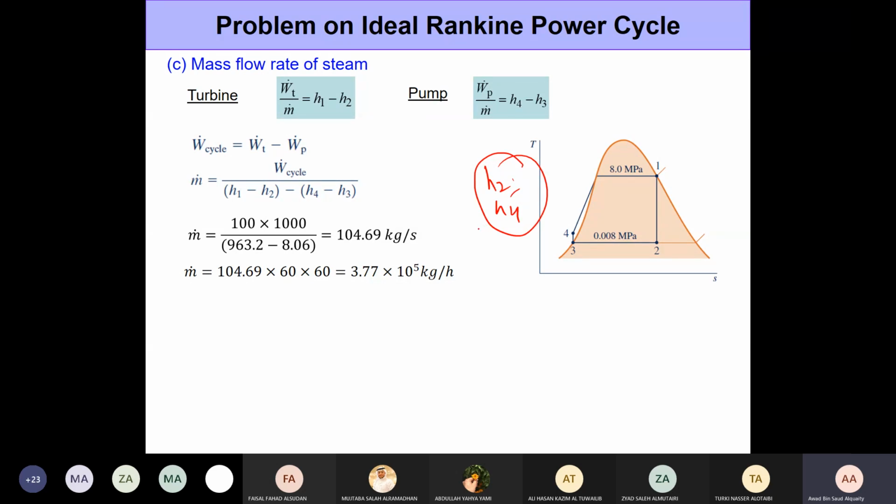Everything else was just a matter of putting in either from the energy balance or using the definitions for enthalpies and back work ratio. Now, we calculated the thermal efficiency of this plant to be 37.1%, but just relying on energy efficiency is not enough. We need to compare it with the situation for a reversible cycle, because just looking at 37.1, it looks like a low efficiency, right? It doesn't look very good. It looks as though we are wasting the remaining 63%, and it's just going to the environment, which is a waste of exergy, right?